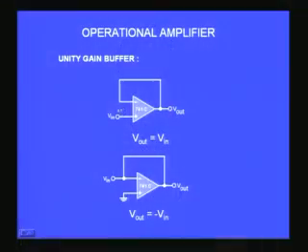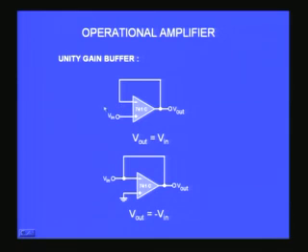But then if there is no gain, why do you talk about this amplifier? We talk about this amplifier because the gain is 1, alright, but the input impedance has increased by an enormous factor of 10 power 5, and the output resistance is decreased by 10 power 5 factor, because I have sacrificed the entire gain in the feedback, and therefore it improves every one of the characteristics by that factor. So if it is a 1 megohm input resistance, it becomes 10 power 5 megohm, which is a very large value, and the output resistance is 75 divided by 10 power 5, which is again a very small value. Therefore it becomes an ideal voltage amplifier with a perfect high resistance at the input, low resistance at the output.